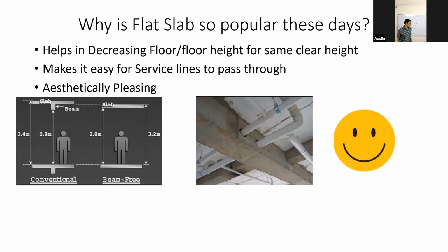Or you can provide your sleeves as Mr. Vansh has suggested, somewhere near the point of contraflexure in your bending moment diagram. At the point of contraflexure, your bending moment is changing its nature, so generally you have a place where you have got no bending moment as such. There you may try to go for a sleeve, but the shear forces there are substantial.